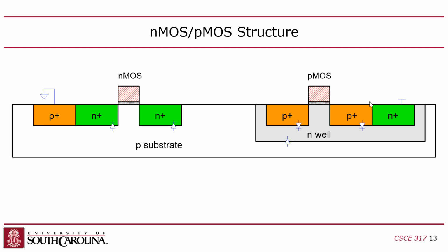So now, when you design a chip as masks, shapes, polygons, right? You design it from the top down. You don't design it from the sandwich cutaway like this, you do it from the top down. But you will have a layer for N plus, the diffusion area. You have a layer for N well. Then on top of the N well, you can put another polygon that's the P plus layer, and then you could put a layer for silicon dioxide, and then you could put a layer for polysilicon.